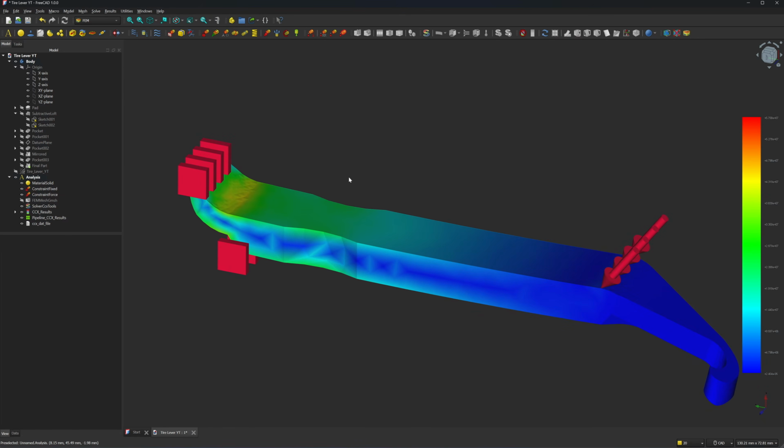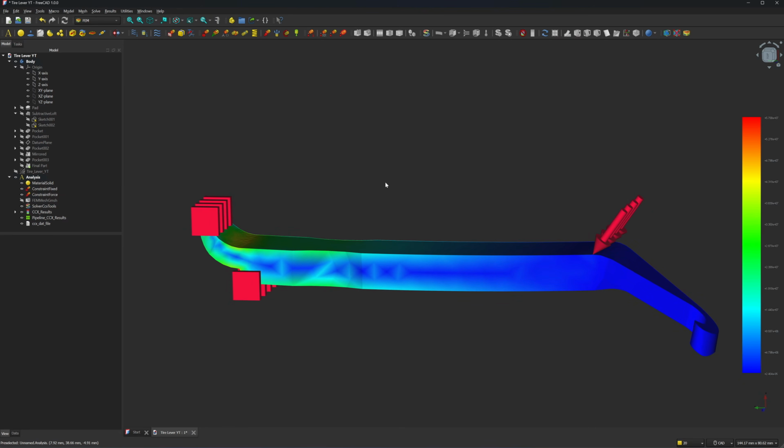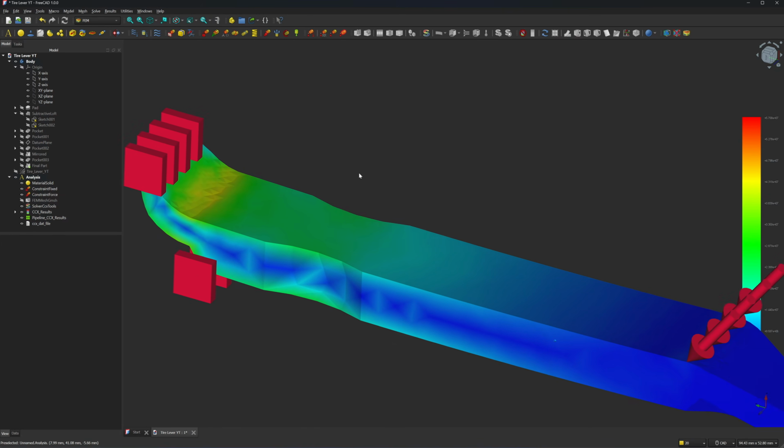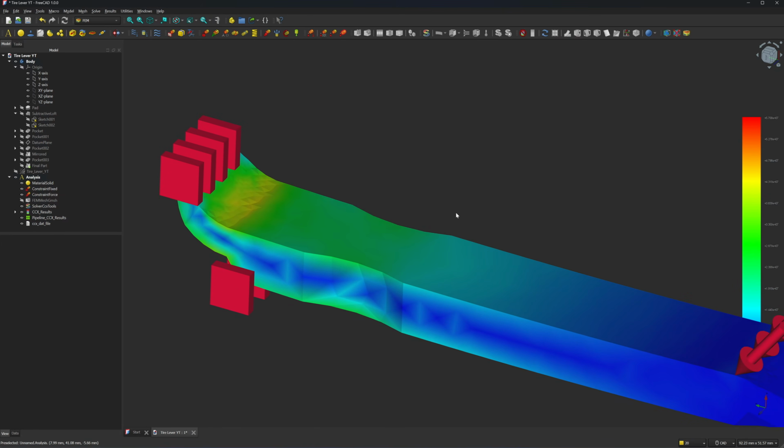So in this design, you don't need 100% infill because the stress from the bending will only appear on the skin of your model. So if you put 15% infill or 100% infill, you're going to get the same result. The outer part of the model, which is the skin, will start to break here first. This yellow, that's 43 megapascal.